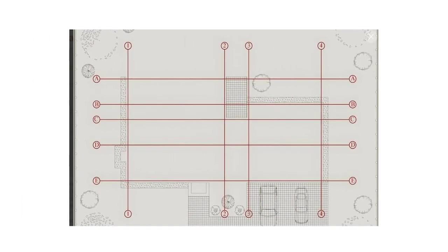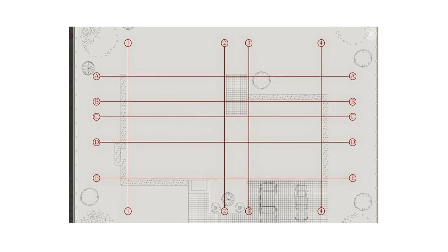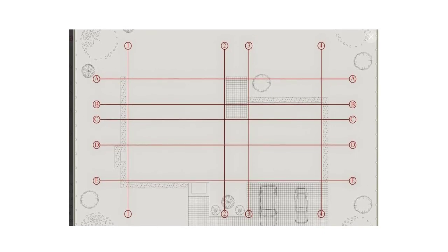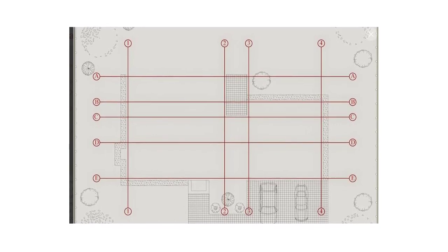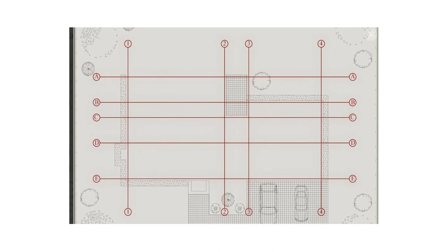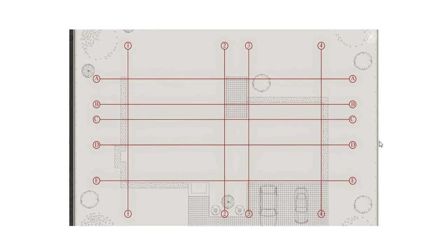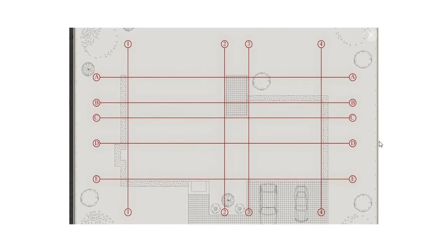If we talk about the grid part, reference grids are like the glue that ties all of the engineering and architectural drawings together. They provide reference points which help the reader to identify the same locations on each discipline drawing set. A row of grids follows sequential numbers, for example running horizontally and vertically, right?